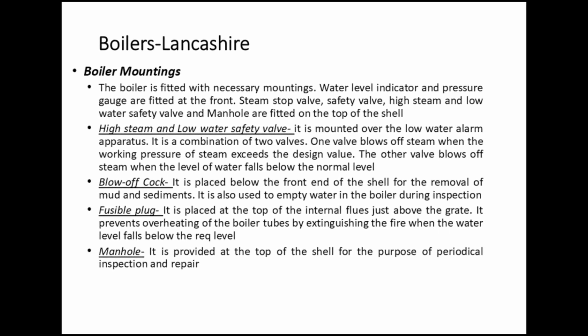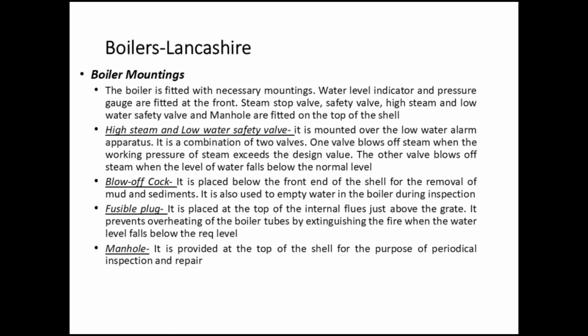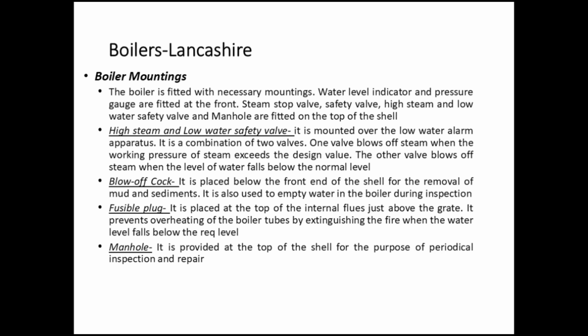Boilers, Lancashire. Boiler mountings. The boiler is fitted with necessary mountings. Water level indicator and pressure gauge are fitted at the front. Steam stop valve, safety valve, high steam and low water safety valve and manhole are fitted on the top of the shell.